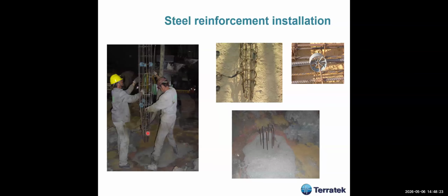Usually this is difficult. If you have a long pile, sometimes it's difficult to install the reinforcement down to the end, and then you do it only in the first 6 meters. This is the case in which, as you see, the tip of the reinforcement is bent a little bit inwards, and there are these rollers or spacers, okay, which facilitate the installation of the reinforcement.